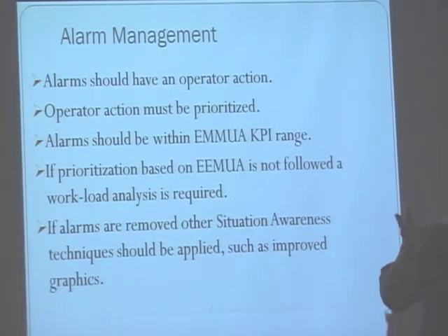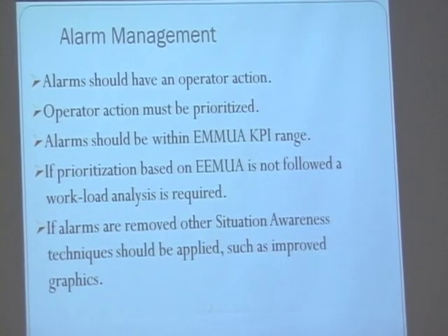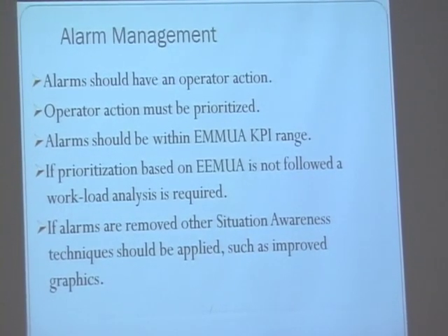In fact, if you go back to some of your panels, you may have had something like 72 alarms for the whole plant. And now with the DCS, because it's easy to add alarms, you've gone from 72 alarms to 4,000 alarms, right? And you aren't any better off. You're actually worse off than having just the 72 alarms, because the alarms just overwhelm the operator.